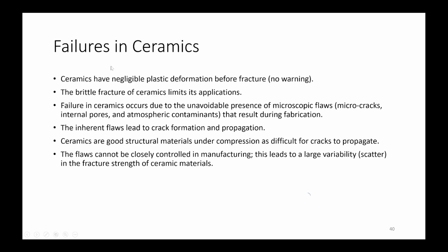Now, failures in ceramics. Ceramics have negligible plastic deformation before fracture. When ceramics fail, they don't show any elongation or plastic deformation before failing. So they don't show any warning, unlike metals, where there is some ductile deformation, so we can know when a metal will fail. The brittle fracture of ceramics limits its application, so that's why we don't use